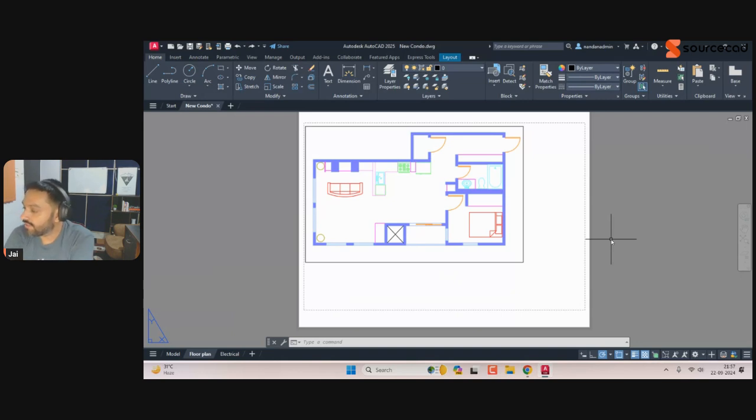Okay. Then we have another question from Edward. Is there a way to change the default paper layout setting, so any layout created in the future uses desired default settings? You can just copy your existing layout. So rather than clicking on the plus icon, you can just make a copy of your existing layout, rename it, and then it's just going to use the same settings.